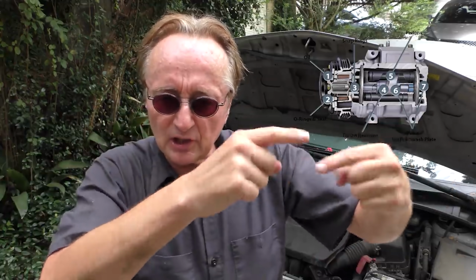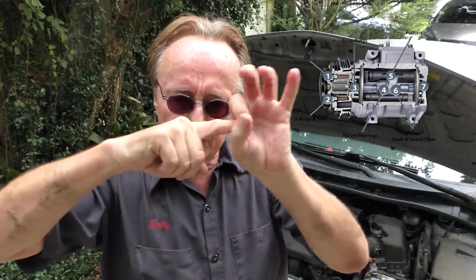Realize all air conditioning systems leak some refrigerant because the end of the compressor spins on your fan belt. That's what runs it, unless you have an electric one like a Toyota Prius, but this is a normal one. So it's spinning the pulley. The pulley has a shaft. The shaft spins the compressor. Well, the shaft has a seal at the end of it to keep the refrigerant from leaking out.